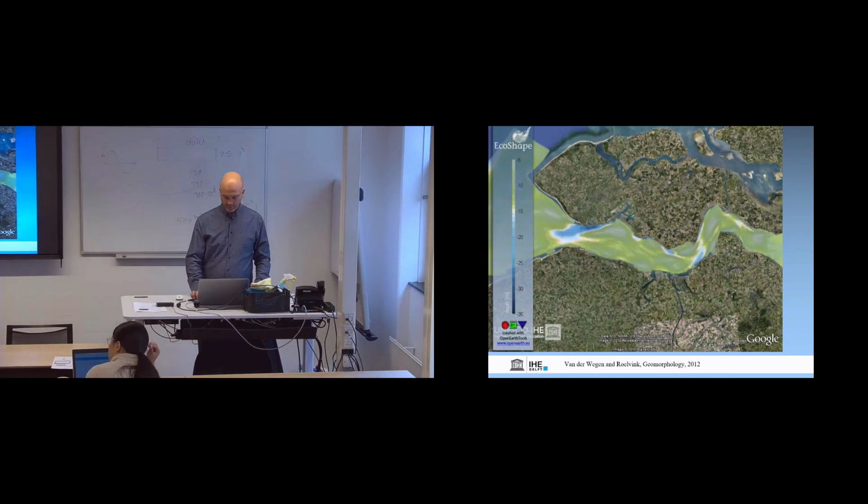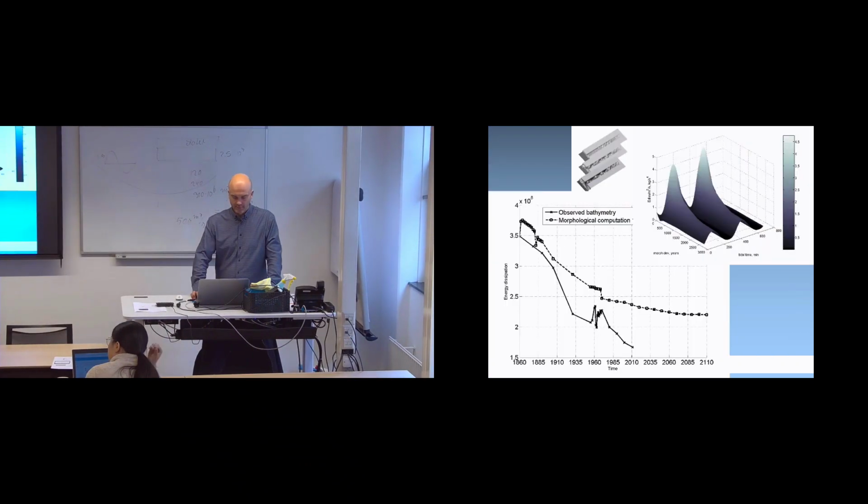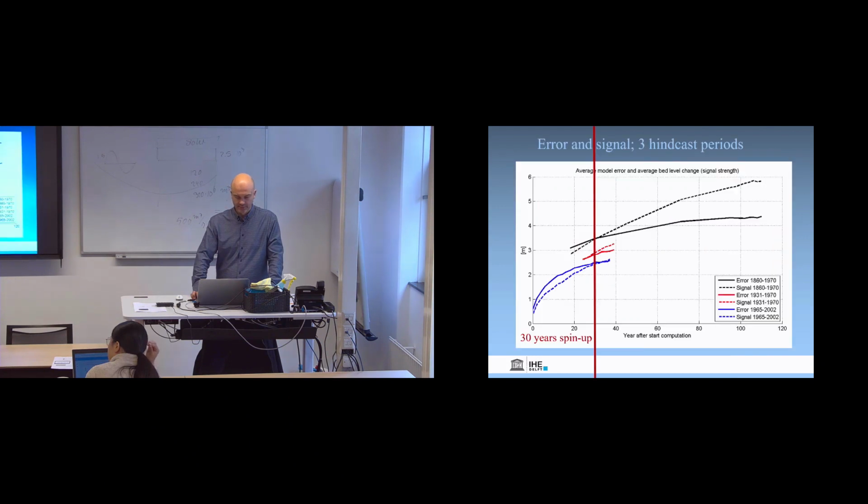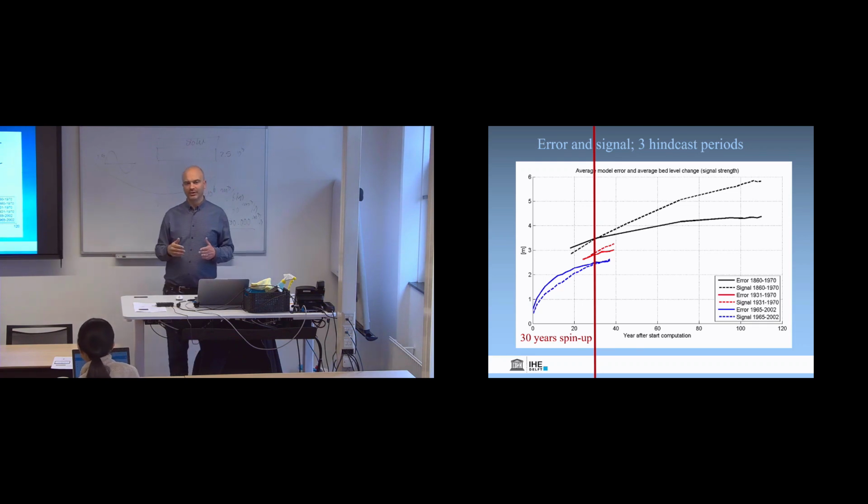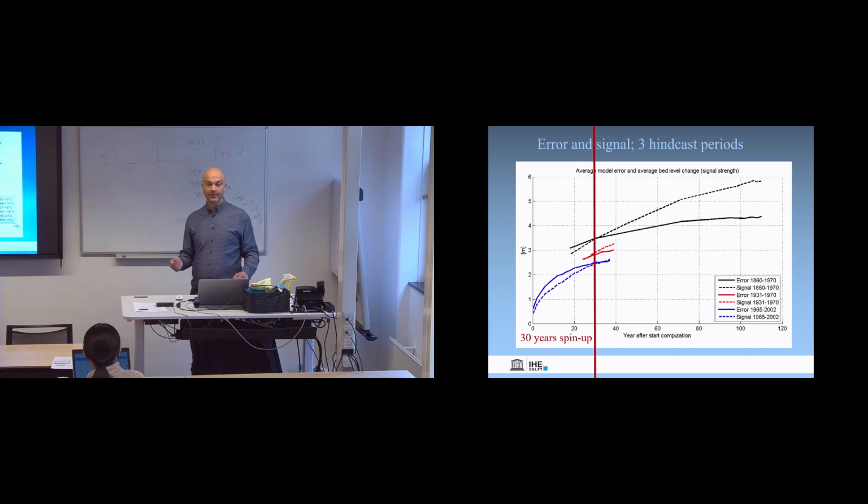So if I have data for like 30 years for the river I'm working on, I will be kind of sure that the result will not be good enough. Well, it's also a case-by-case thing. Usually the morphodynamic development in tidal conditions is slower than river conditions, because river is in one direction, tide is back and forth. So typically the morphodynamic adaptation timescales are an order of magnitude smaller in tidal systems than in river systems. So 30 years maybe quite nice.